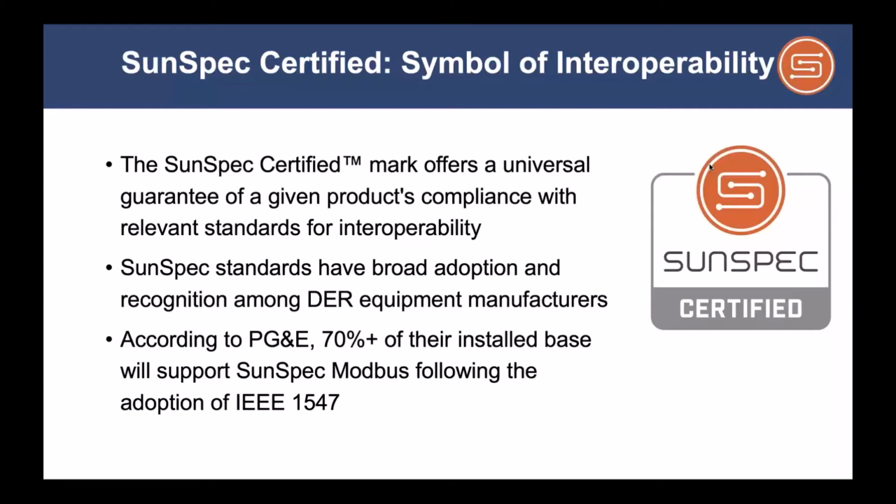And so why is that? Well, again, the Modbus interface is the one that's designed for field area networking. Modbus is also included in most of these core machines. So adding the SunSpec information models is in fact the easiest thing to do to gain this type of compliance.